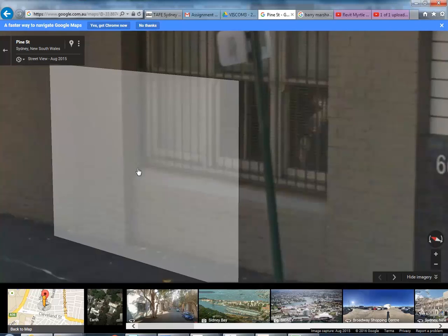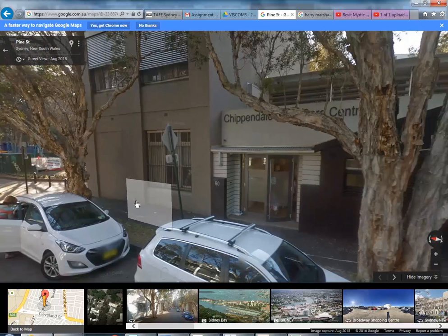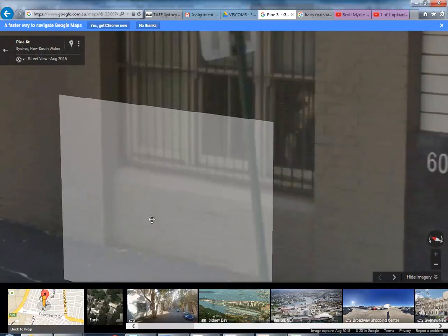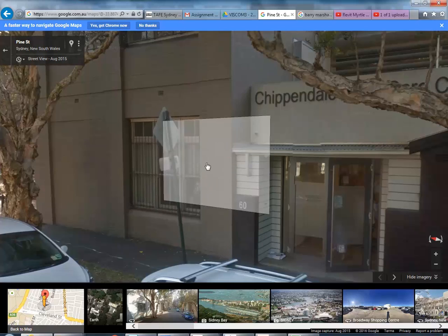So that's with mortar. And so 86, we'll say, times 10, 860. So that's close enough to 900. So we'll say 900 that I measured in AutoCAD, that sounds like a good height. Because obviously the height here would change a little bit with the footpath changing as well. But that's a good tip. When you see something with bricks, bricks are usually a standard height, and you can use those as a measuring rod.